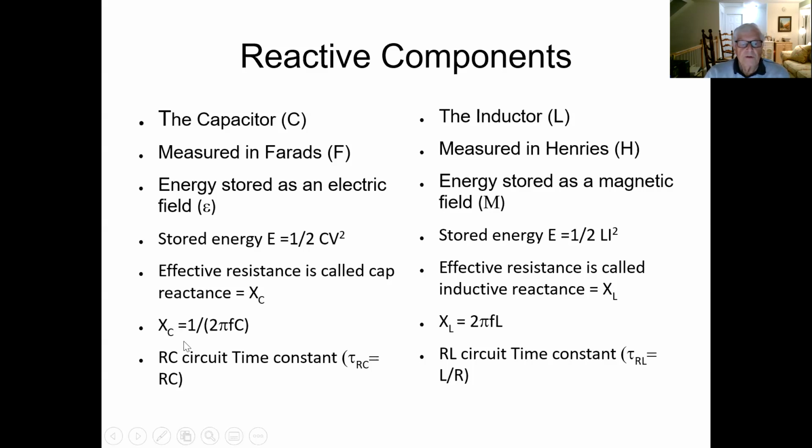And that value is going to be inversely proportional to the frequency and the capacitance for a capacitor, but directly proportional to the frequency and the inductance for an inductor. An inductor is measured in henries, and the inductor stores its energy as a magnetic field, and its stored energy is a half L times I squared.